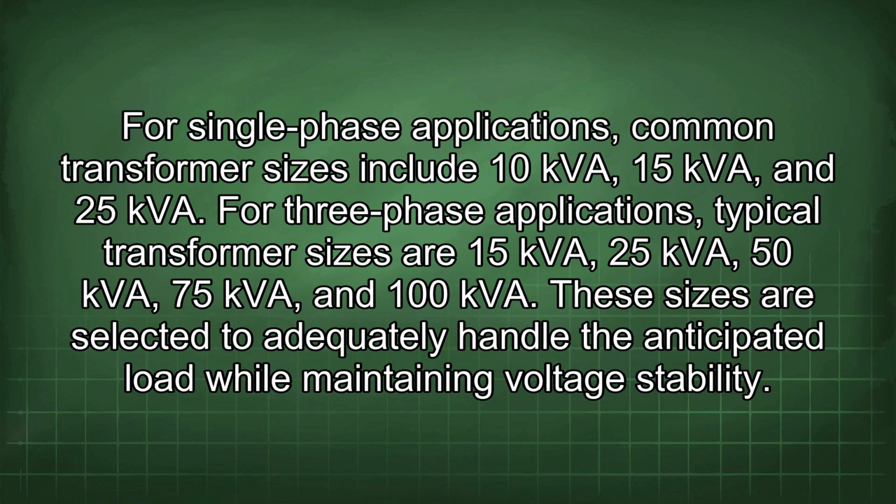For single-phase applications, common transformer sizes include 10 kVA, 15 kVA, and 25 kVA. For three-phase applications, typical transformer sizes are 15 kVA, 25 kVA, 50 kVA, 75 kVA, and 100 kVA. These sizes are selected to adequately handle the anticipated load while maintaining voltage stability.